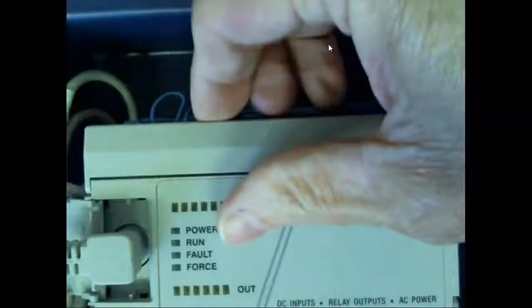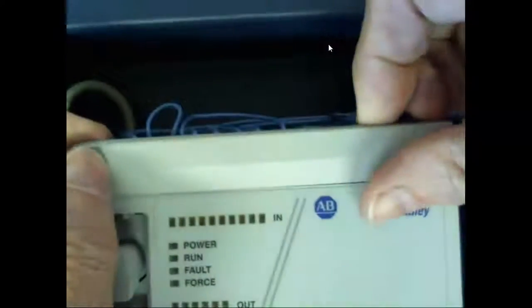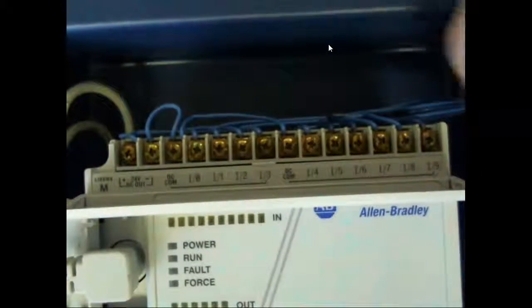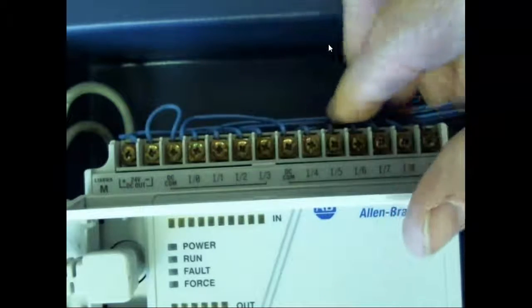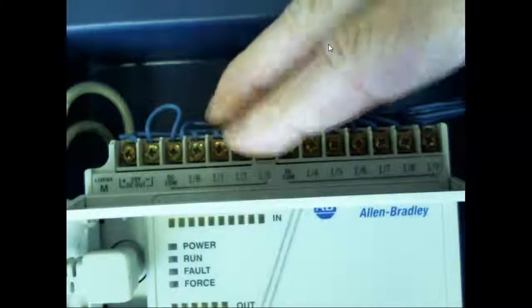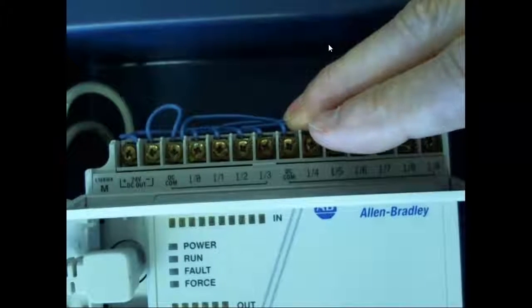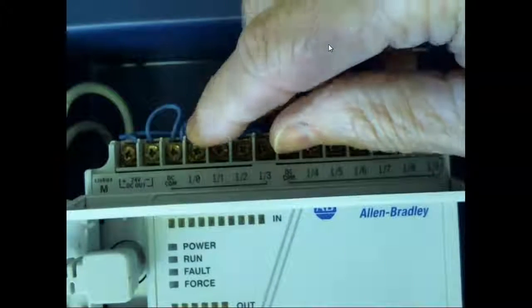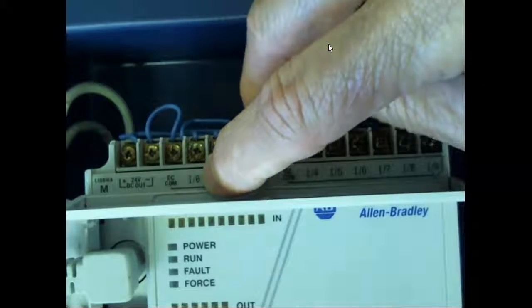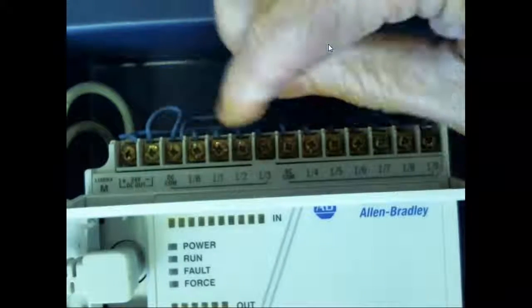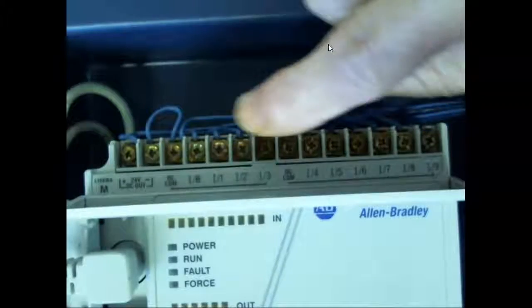Okay. This is the actual input ports. We'll show you how we can wire this up. Okay. And this has inputs 0 through 3 and then 4 through 9. So this has 10 inputs on it. Everybody okay? And that's important to know because that's what we have to know to actually address this one right here. And notice it's got two right here labeled DC common. Can you see that? Yeah, right here.